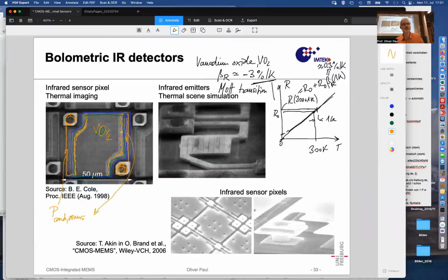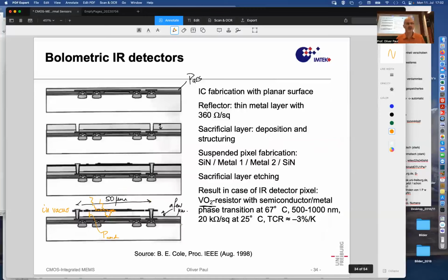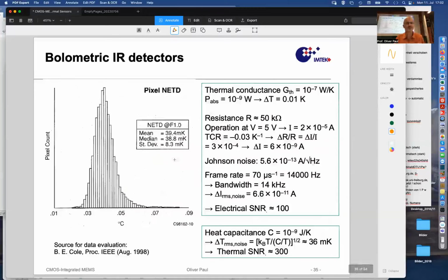And then you are still facing, in addition, P radiation loss, because this is a gray body of some epsilon that loses its energy also by radiation if it's heated up over the temperature of the environment. The delta T makes it happen. This formula of 4 or 8 times epsilon times T0 to the cube times delta T that we developed earlier comes to bear here. So eliminating loss channels is important, and that means that this structure is operated in vacuum.